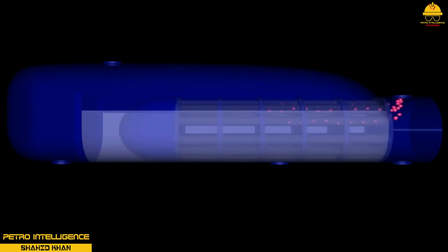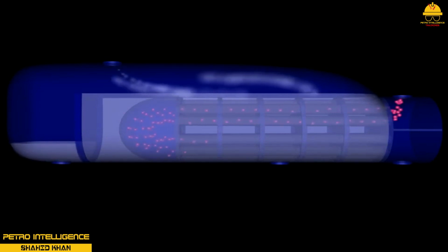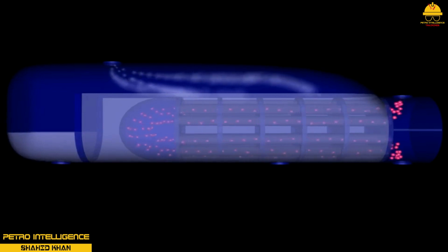Kettle reboilers operate with liquid levels from 2 inches above and 2 inches below the upper tubes. Engineering designs typically allow 10 inches to 12 inches of vapor space above the tube bundle. Vapor velocity exiting the reboiler must be low enough to prevent liquid entrainment. Bottom product spills over the weir that fixes the liquid level on the tube bundle.